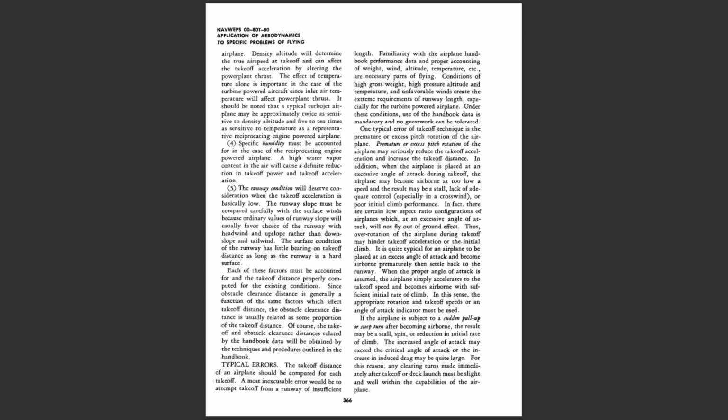The increased angle of attack may exceed the critical angle of attack, or the increase in induced drag may be quite large. For this reason, any clearing turns made immediately after takeoff or deck launch must be slight, and well within the capabilities of the airplane.